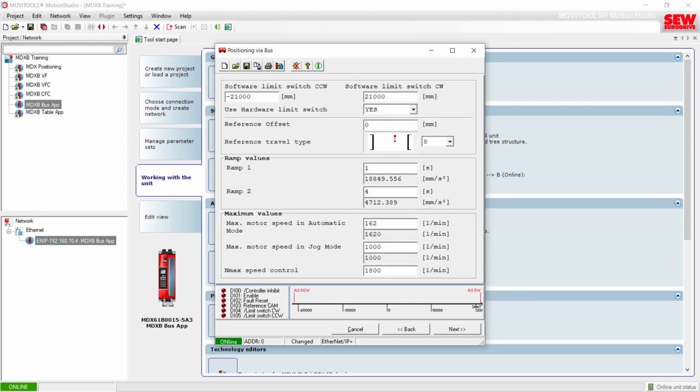You see, if I go to 1621 and press enter, the red box returns. So the 10% equation is 10% of the speed controller, not 10% of these values here. So just know that if you see a red box, it means that your speed is too close to the speed controller maximum allowed. Let's change this back to 2000 RPM and then change this back to 1800.